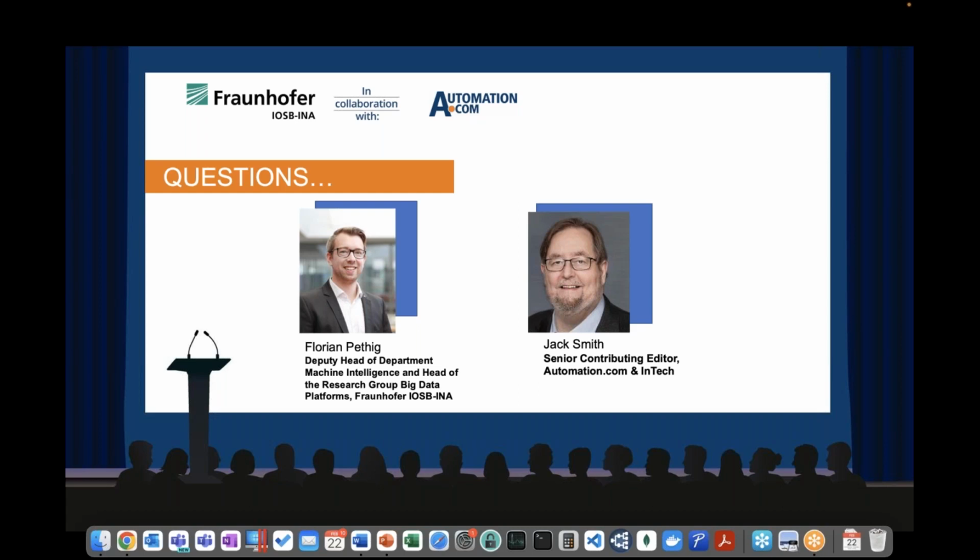What else was considered as an alternative to MQTT, if anything? Well, in OPC UA PubSub, you, for instance, also have another broker-based approach, which is AMQP, which stems more out of the financial sector and is not so popular for IoT scenarios. I hope I got the question right.